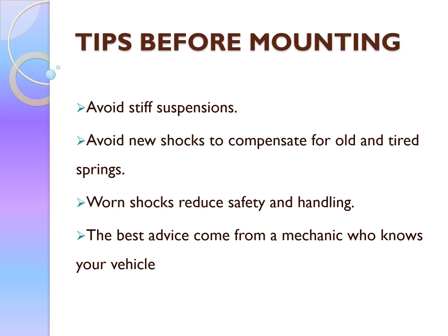And some tips before mounting. A stiff suspension does not necessarily mean good handling. Often the contrary; if a stiff suspension is needed, it should come from the springs. The function of the shock absorber is to dampen oscillations of the spring by converting energy to heat. Do not use shock absorbers to obtain a stiff suspension. Shock absorbers and springs each have their own function. Avoid stiff suspensions. Avoid new shocks to compensate for old and tired springs, as it reduces safety and handling. The best advice comes from a mechanic who knows your vehicle.